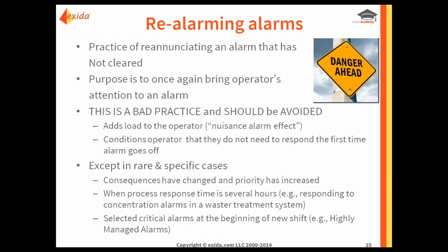Another area that's covered in the technical report relates to re-alarming alarms. Now, if you've listened to any of the other alarm management webinars, you might think, what are we talking about? The idea of re-enunciating an alarm that has already been presented or is not cleared to draw the operator's attention to it seems counter to everything that we talk about related to the importance of an alarm and the operator responding to it the first time it occurs.